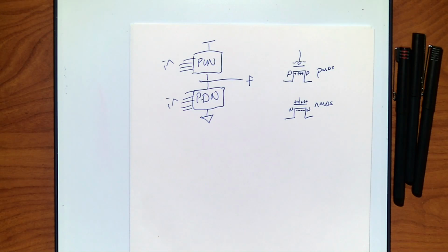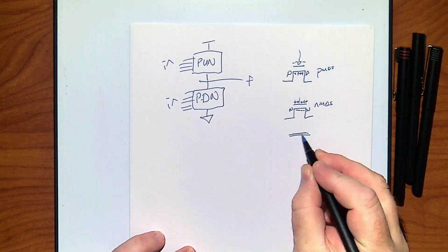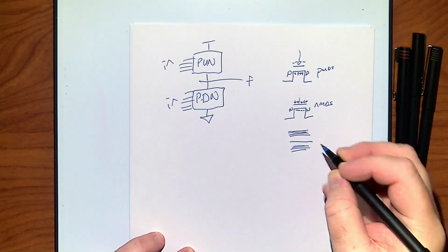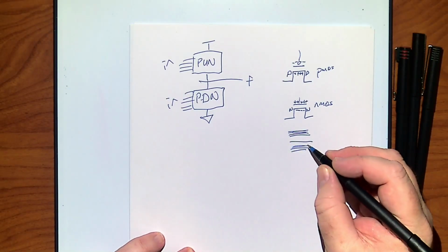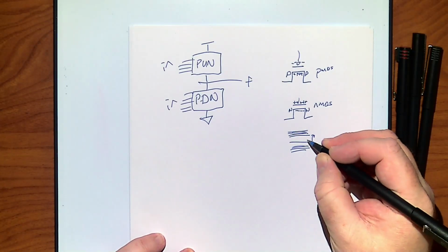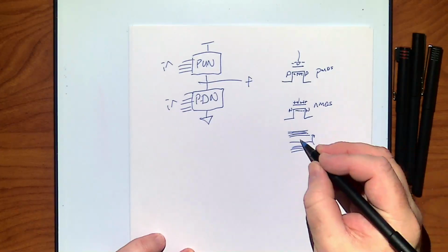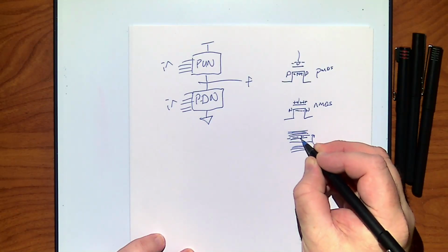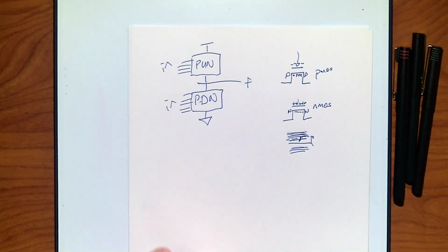Now, think about how I get flow using electrons. Go way back to day one: how do I get electron flow? I've got the conduction band and valence band, Fermi energy somewhere in between. What I want is something to get promoted up. What we usually do when making N types is add an extra little layer up here, which raises the Fermi level. It's a small jump up, and then the electrons are free to move up the band.